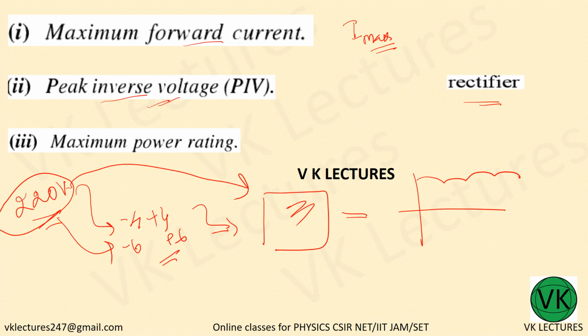That means not only peak inverse voltage, even a higher positive voltage, if we use it, is a problem. Our diode will get damaged. That is one reason why we are stepping it down. Another reason is, if we use 240 volt for rectification, your college will be history.